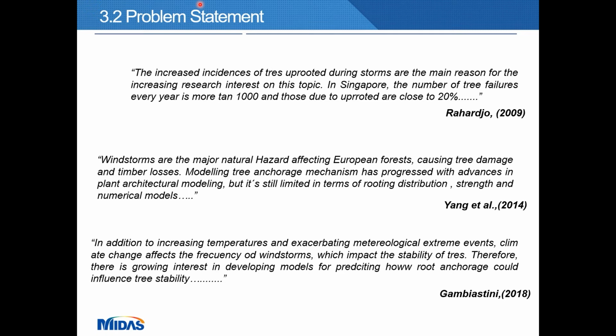So in this webinar, we will see a brief summary of a study where we analyzed three tree species commonly found in Singapore. The one I'm going to show all of you is the Samanea saman. We started using static loading tests, air spading, and laser scanning for the resulting geometries. And we tried to combine all this data that we gathered, and we analyzed it via the finite element method using MIDAS GTS NX. We also have strength properties and soil properties in order to understand the behavior in place.